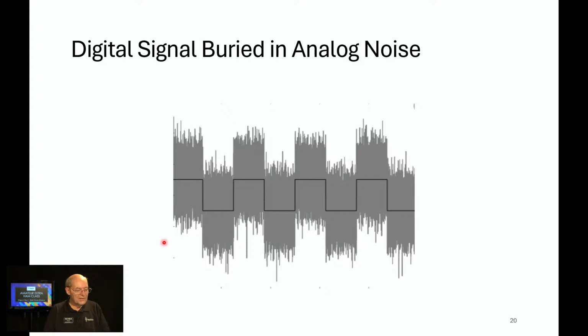And we've got some really interesting things that happen. Digital, I'm thinking of FT8 right now, other digital modulation systems as well. The signal is buried in the noise. So if you were listening to this, you wouldn't even be able to tell that this signal was in there. We're showing a square wave here, but of course it's some kind of a modulated digital signal, completely buried in noise. But DSP, through various techniques, can actually pick out the signal that's hidden in the noise. That's one of the reasons that FT8 will work well below the noise. You can't even hear it, and it's decoding.